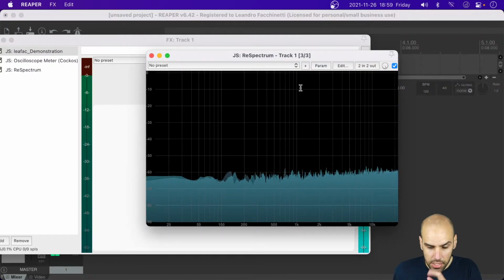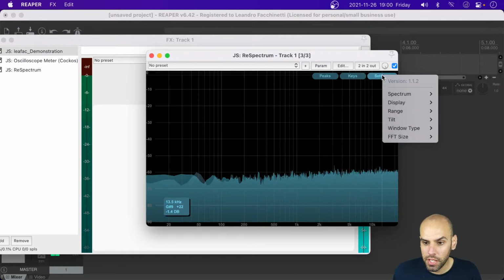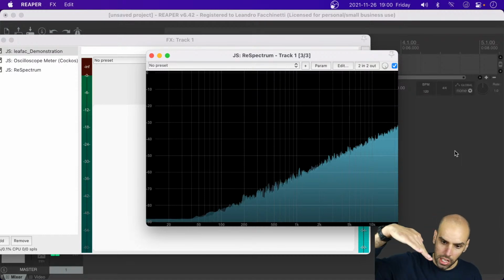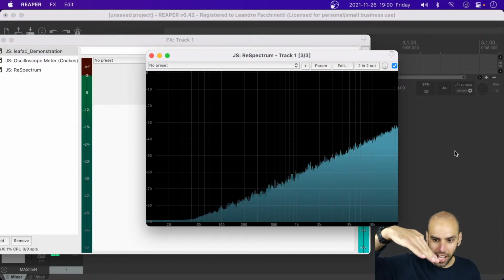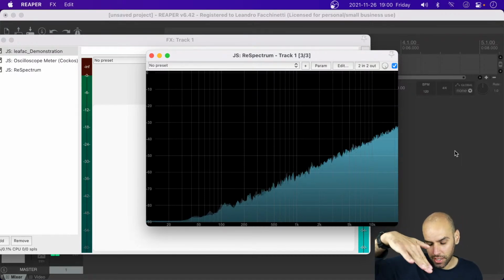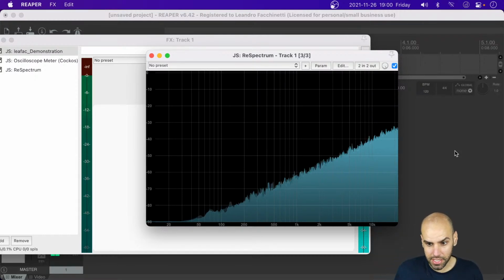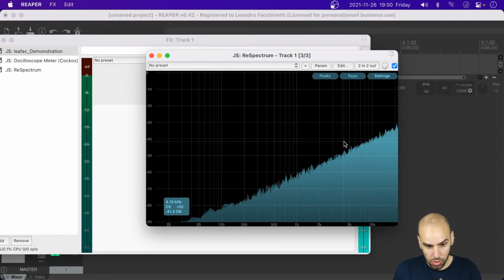But I'm using this spectral analyzer because it comes with a convenient feature called a tilt. So I can tell the whole analyzer to tilt by 6 dB. And now what was a flat line is now a line with an angle of 6 dB. And this is a positive angle. So now this is white noise with a 6 dB tilt. And we will know that we succeeded to create Brownian noise if we turn this into a straight line.